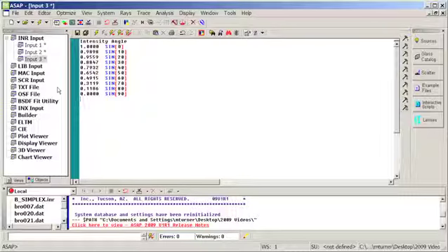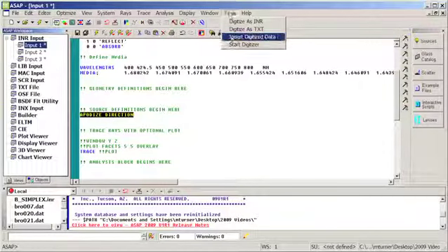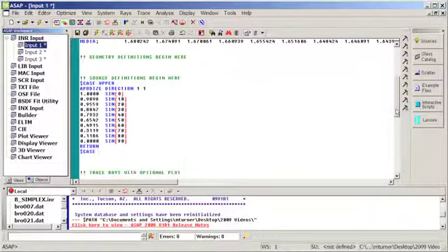We could save this as a library file for later use, but right now let's insert the data within our ASAP INR file. So again, with apodize direction highlighted, I'm simply going to go to Tools, Insert Digitized Data, and now we have our data in proper ASAP format inserted for us right in our ASAP file. For now, the context-sensitive digitization is limited to media and apodize commands, as well as several forms of the coding command. We do plan on expanding these capabilities in future releases of ASAP.